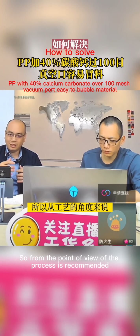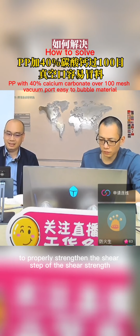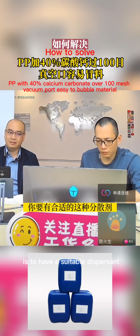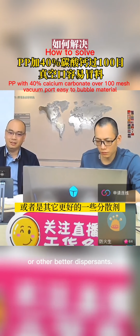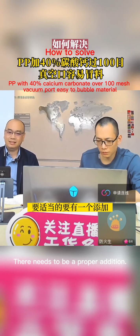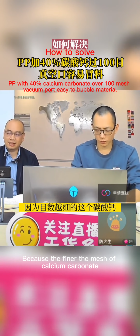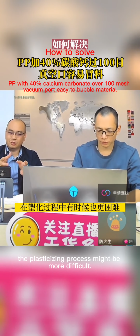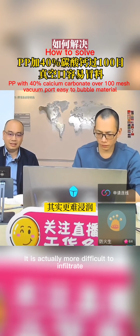So from the point of view of the process, it is recommended to properly strengthen the shear strength, which is the first solution. The second solution is to have a suitable dispersant, whether it is a more branded one such as EBS or other better dispersants. There needs to be a proper addition. Plasticization must be guaranteed. Because the finer the mesh of calcium carbonate, the easier it is sometimes to clump together, and the plasticizing process might be more difficult. It takes more time to be done. Call it infiltration. It is actually more difficult to infiltrate.